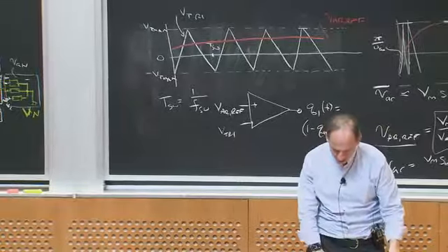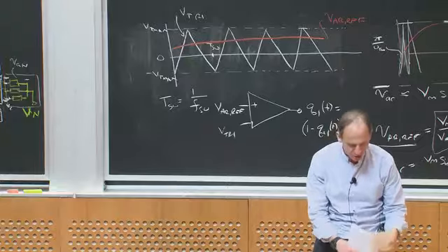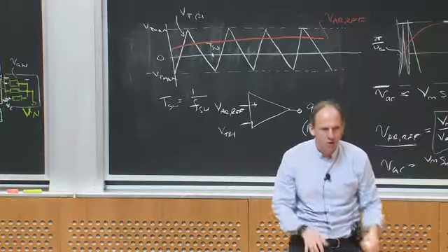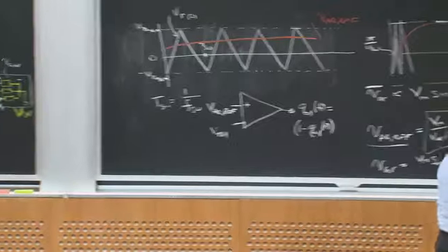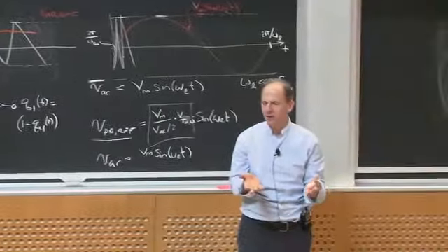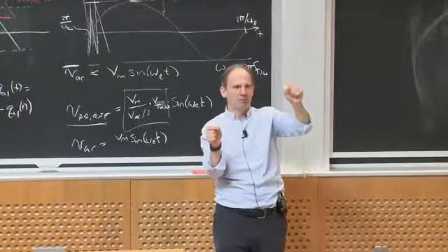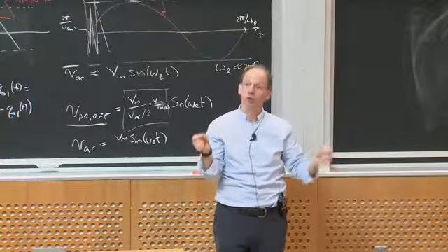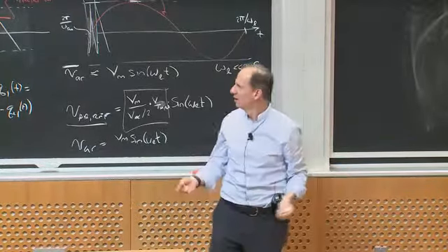This technique is very good when we are trying to synthesize a waveform with a lot of purity, right? The 6-step waveform I showed you before had a ton of low-frequency harmonic content in it.